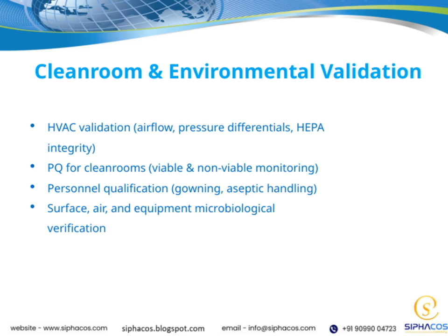Regular testing helps us detect any microbial presence early and address issues before they affect product quality. All these aspects, HVAC, PQ, personnel qualification, and microbiological testing, are interconnected. They form a comprehensive validation strategy that supports our overall goal, maintaining a sterile, controlled environment to ensure the safety and efficacy of our products.